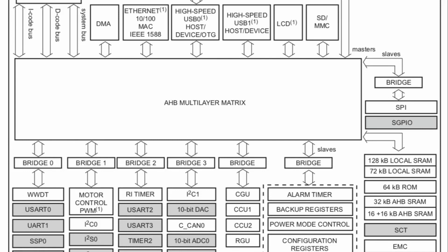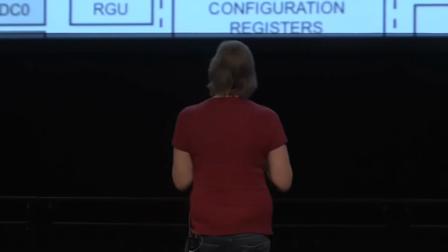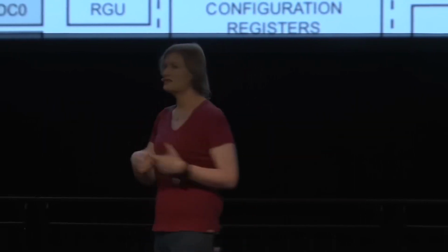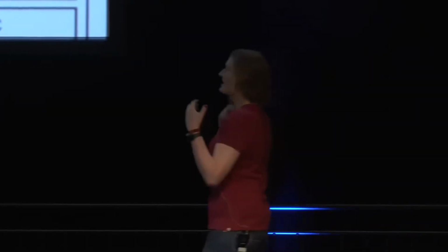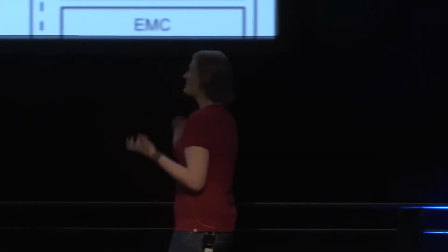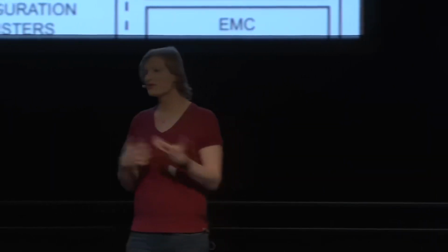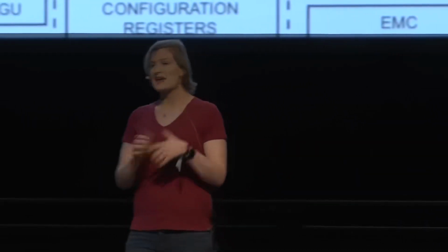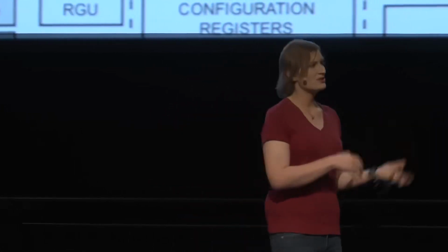So the challenge as an attacker is if I take a device that has a lot of these buses populated, I take a board that is using USARTs and it's using a UART and it's using USB and it's using the SD port and it's connected to an eMMC card. If I want to start breaking into that device, I have to build purpose-built triggering hardware right now that is capable of identifying exactly when those individual peripherals are being used and for what.